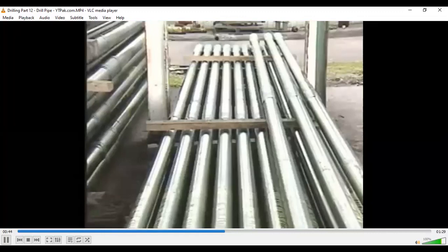The bottom hole assembly includes all of the tools below the drill pipe and above the drill bit. These tools promote drilling objectives in a number of ways. Drill collars maintain tension on the drill pipe, provide weight to the drill bit, and stabilize the bit as it turns. Heavy-walled drill pipe helps prevent drill pipe fatigue failures by providing a smooth transition between the drill pipe and the drill collars. It also aids in directional control.